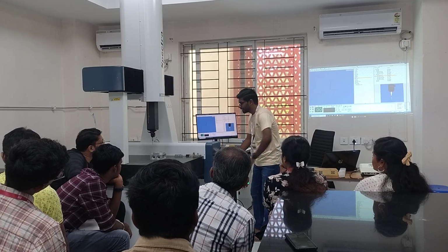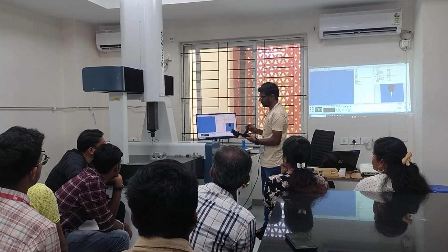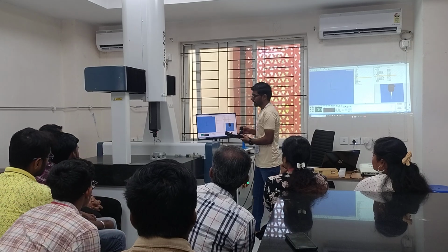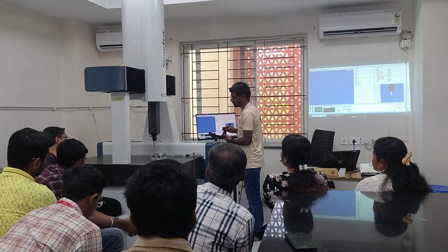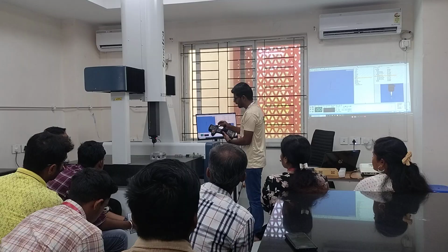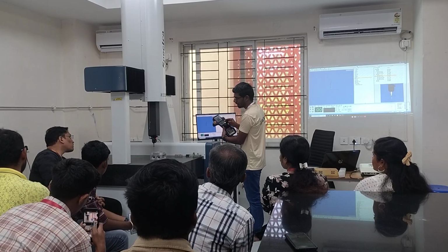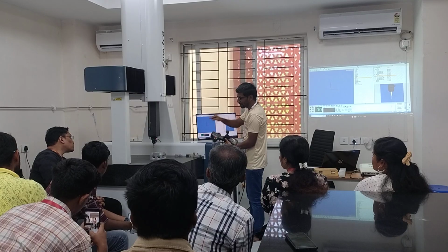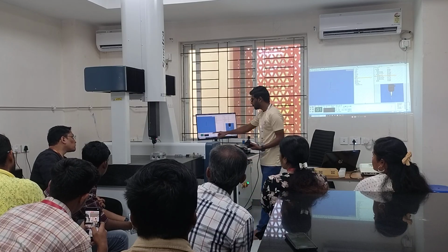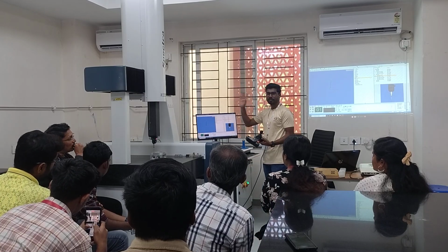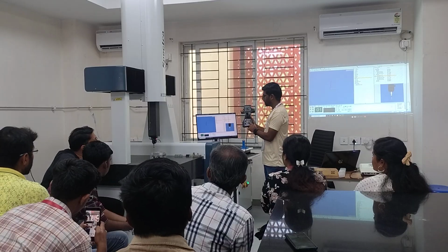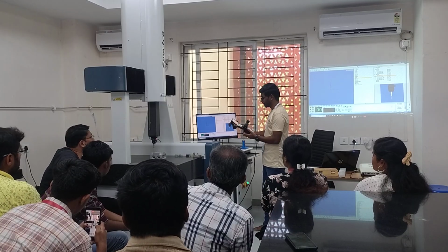Okay. So I'll just touch one of the bodies on the top. I'll move down and see. I'll keep the override very low, because it is going closer, and then I'll move down. It is touching and coming 5 mm above. So one point is already taken. If I want to remove that point, I can do it here. So it is cancelling. It is not taking that.